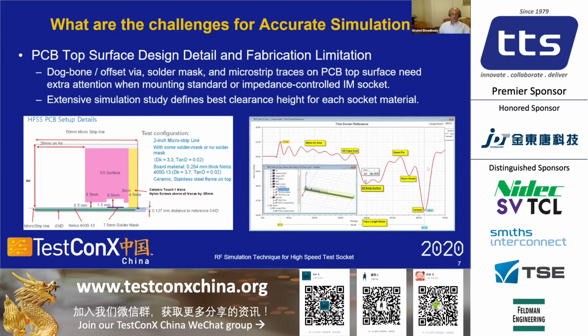So definitely you can change the dielectric of this material to get less effect and try to minimize the impedance mismatch as much as possible, make it plus or minus 3 ohm as best you can. With this extensive study, we obtained the optimum gap between stainless steel, between plastic, between different materials of plastic above the PCB.